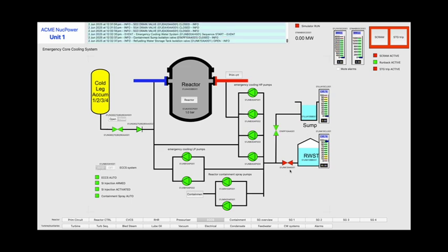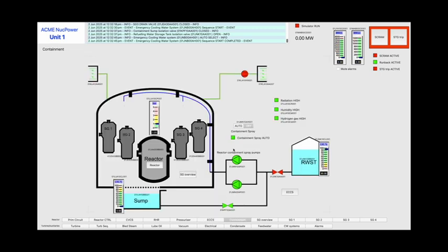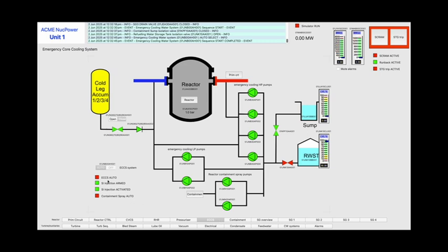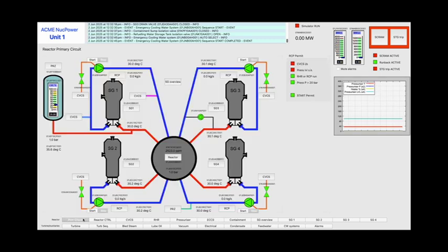Next we need to look at some of the safety systems that must be started before we can go critical with the reactor. So go to the emergency core cooling system page and place it on automatic. This system will ensure that if a leak occurs in the primary circuit that additional water will be pumped into the circuit and prevent the reactor core from drying out. Here we select to automatic the containment spray pumps. There is one final part to this safety system, but we cannot place it in service yet. We will come back to it later.